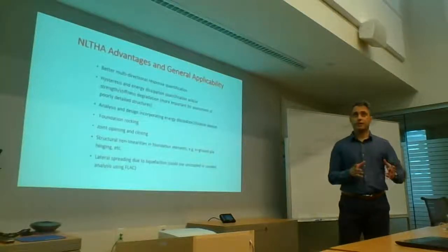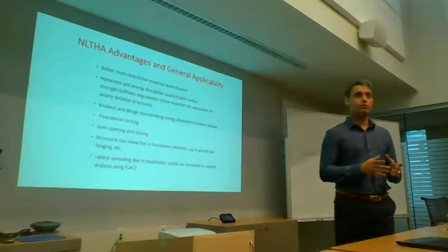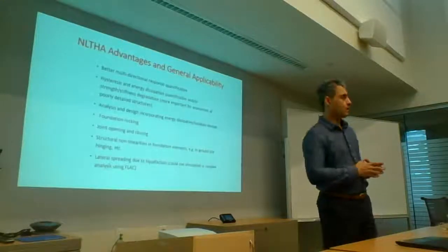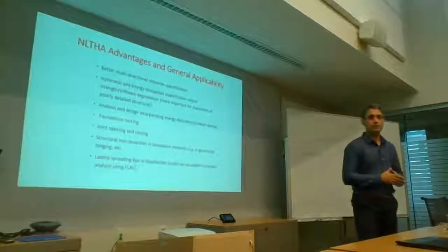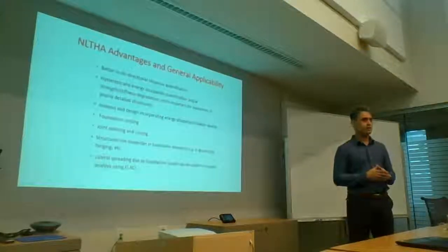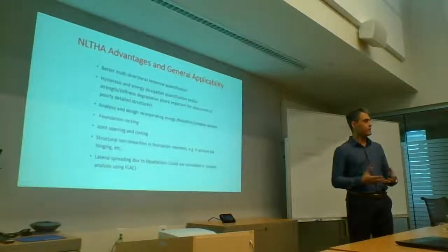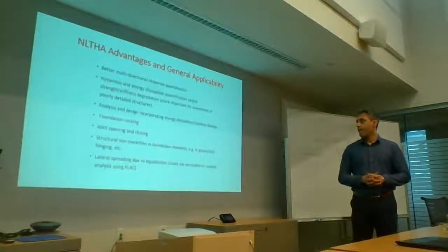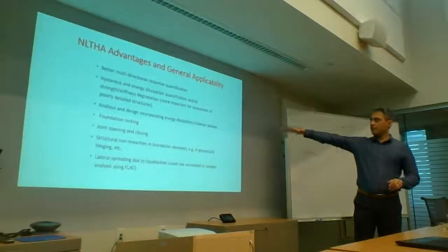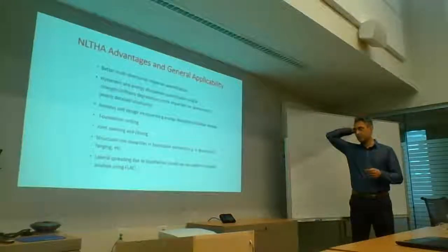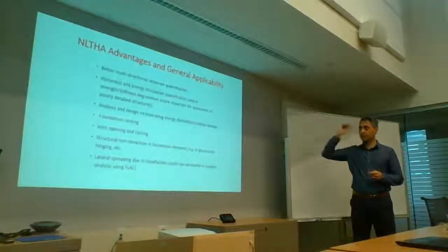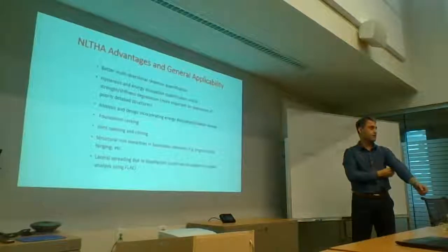Usually response spectra will give you, I don't want to say they're always conservative, but a lot of the times you find that when you run the time history analysis, your demands come down a little bit. Okay, now in terms of other analysis, like if you've got dampers and isolation devices, it's probably best to use the nonlinear time history analysis.